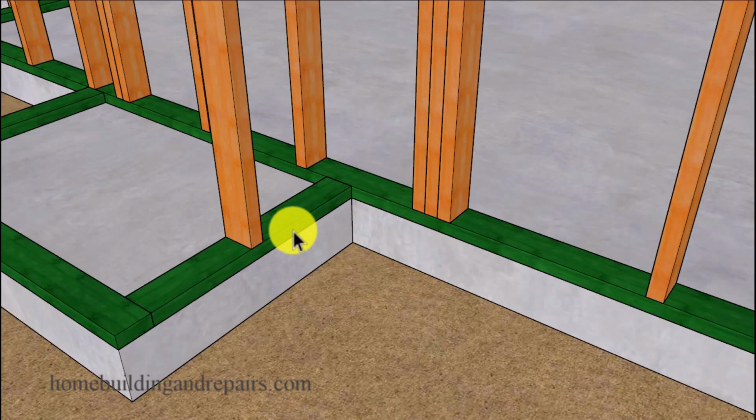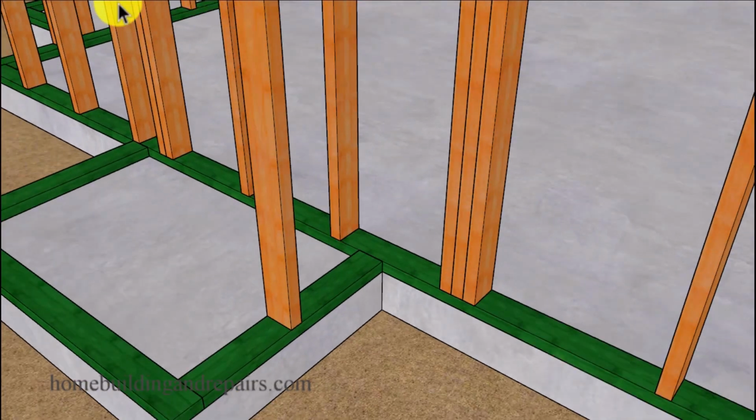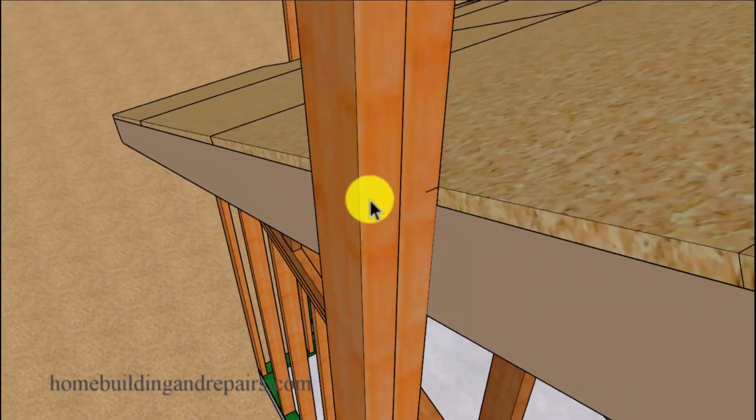Or you could always measure from here to the fascia board on the top and transfer that measurement to the bottom. And you don't need to be right on the money here. I think as long as you're within an inch, you're going to be okay. I'm also nailing two 2x4s together here to provide those of you with another option if you can't find lumber long enough to calculate the chimney stud height.